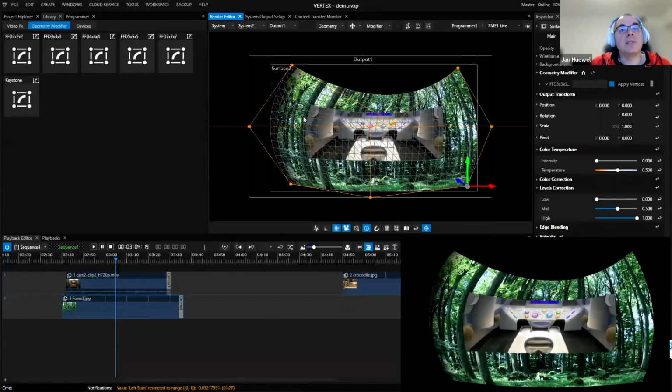There are these FFD modifiers, and the FFD modifiers also work as a stack. So multiple modifiers can be combined on the same surface. You can have a sub-selection of points that can get a different modifier. And that's where you can really have fine-grained control over how you do the warping. This change would be made here on the selection vertices UV. So you can really determine on which level you work on an object when you do blending and warping or just deformations. And all these parameters can also be animated.